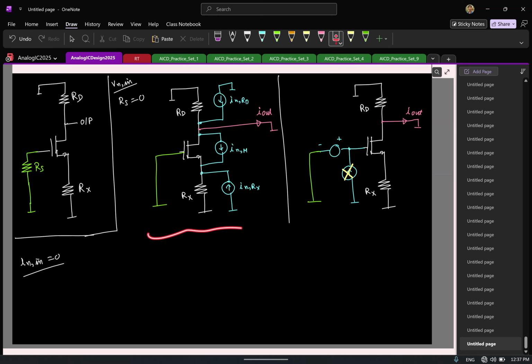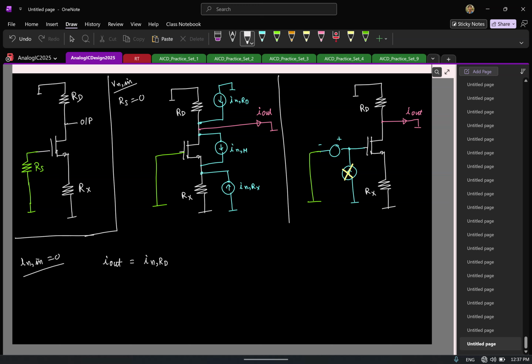So let's start finding the output noise spectral density. Let's start with simple. What about the contribution of RD? I mean this current source. That completely flows. So let me write it here. I out, due to the current source INRD, the entire current flows, no confusion. Then let's look at other things one by one. This I'll remove for now because we have accounted for it. For now, let's ignore this. Consider only this current. Maybe I'll erase this also.